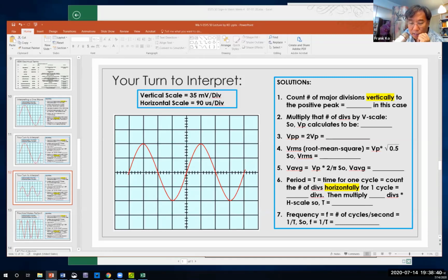Okay. What does volts peak to peak tell us? Volts peak to peak just shows us whether or not we're going to exceed the scale of our display. And so by knowing volts peak to peak, there's certain settings on the oscope that we can magnify the waveform without changing its amplitude.